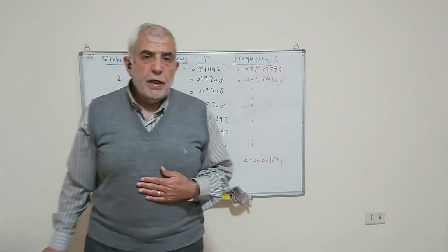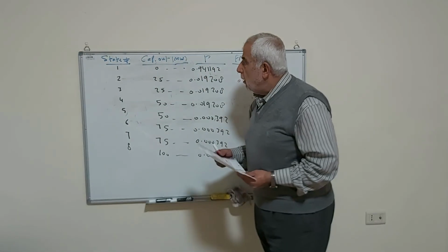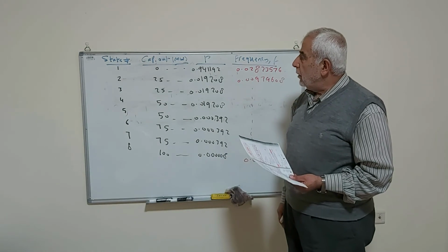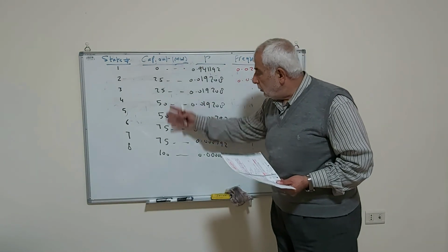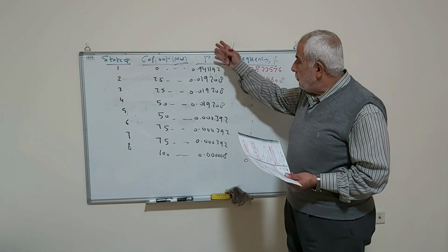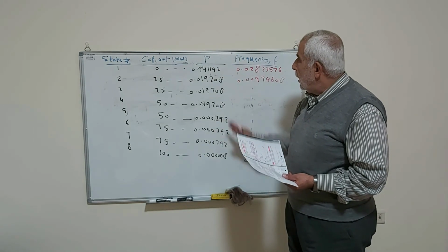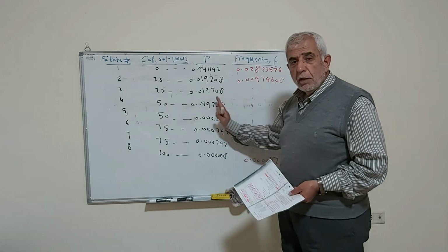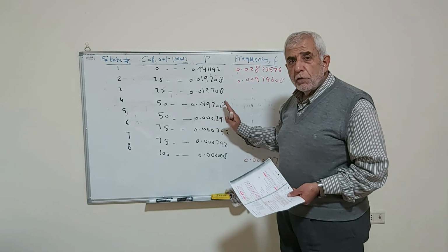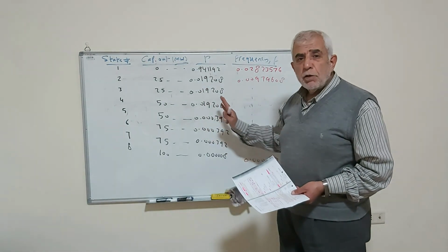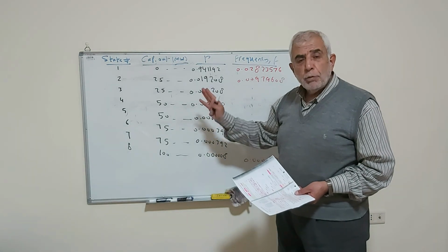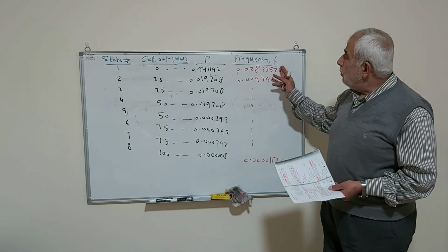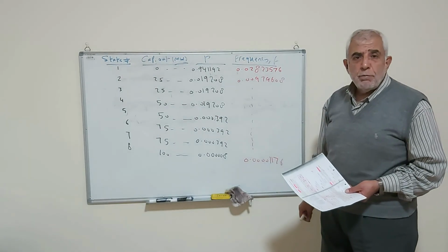So in our case, we have the so-called generation model, because it is the capacity out and it is a probability. Up to here, this is the model used for the loss of load expectation and the loss of energy expectation. But what have we now added? We have this column which gives the frequency of occurrence of each capacity on outage.